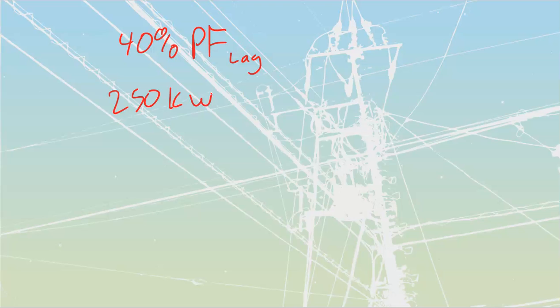And what we need to do now is convert that power factor to unity. In other words, we need to take out all of the capacitive vars. So we need to just find capacitive vars. That's all that we're trying to do. They're not asking us for line current or anything like that.